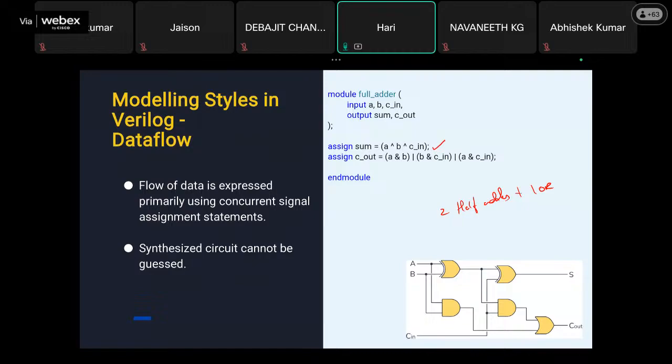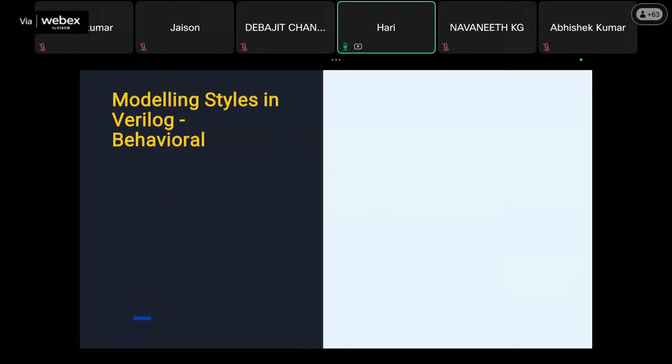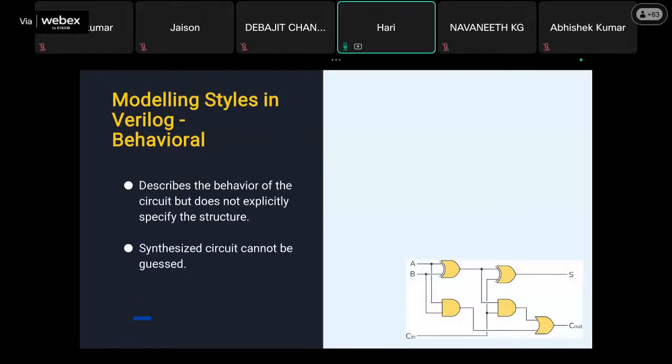So similarly, even if you define two half adders plus one OR gate in a structural way or in a data flow way, Quartus, or your Verilog tools, is very intelligent and understands this is nothing but a full adder. So you can also try out how this particular software is now able to recognize other different designs. Apart from it, we have one more design, which is behavioral.